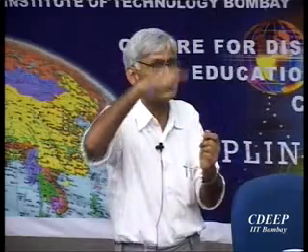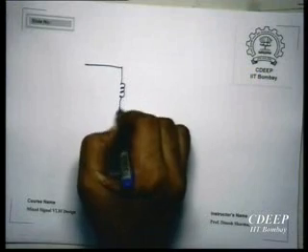Capacitor in series, but that won't do, because if you put a capacitor in series, you will get only a pulse. Okay, you won't get a level. So what you can do is put an inductor in series with the load, with the terminator. Okay, so if you put an inductor through which the current is flowing, so I have a current mode signal, right? And if I put an inductor here,